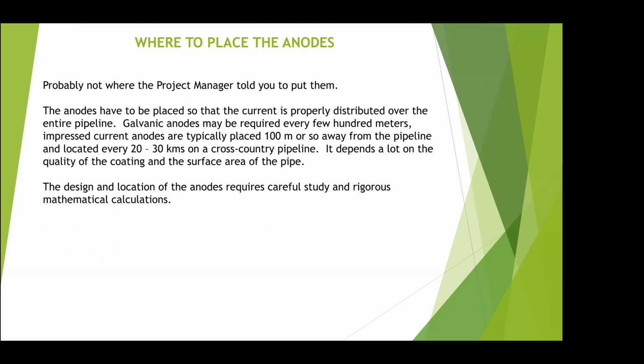I can tell you from experience, it's not where the project manager tells you we wish you to put them. Because it's quite an art. And one of the things I found useful to explain to people about this is, if you think of the anodes as electron pumps, and if you think of a flashlight as being an electron pump, which it is basically, if you turn a flashlight on or a torch and you hold it very close to the wall, you'll see one very, very bright spot.